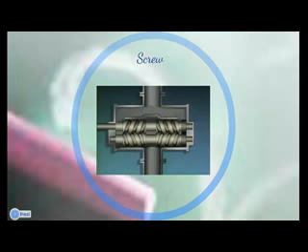Power is transmitted from the driver screw to the other screw, which is the idler screw, through a set of timing gears. Fluid that enters the pump is directed toward both ends of the casing and is trapped between the casing and the screws as the screws rotate. The fluid is moved from both ends of the pump toward the center, which is also the pump's discharge.